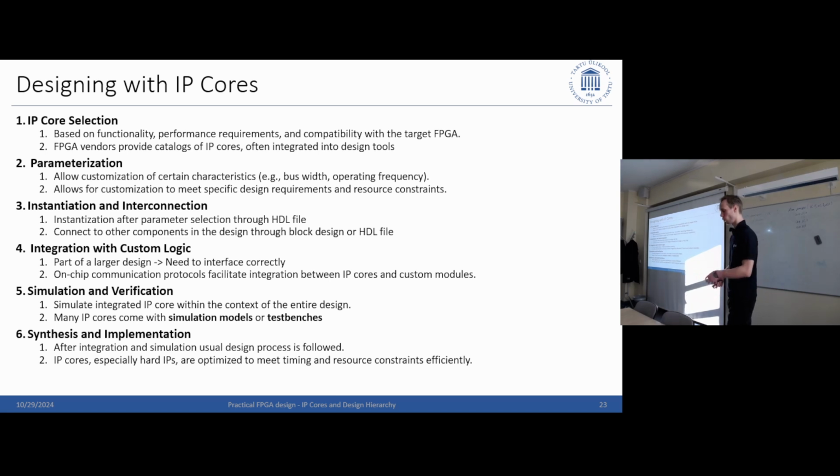Also, overhead-wise, very important, as we talked about with HLS or block design: the higher my abstraction level is, the less customized to my specific need it will be. So I might have a huge overhead which will take half of my FPGA, but actually could have reduced it to a quarter or whatever, right? Because I do not need this functionality, and that is still in there and I will never use it. So the choice of your IP core and what it will do is very important.